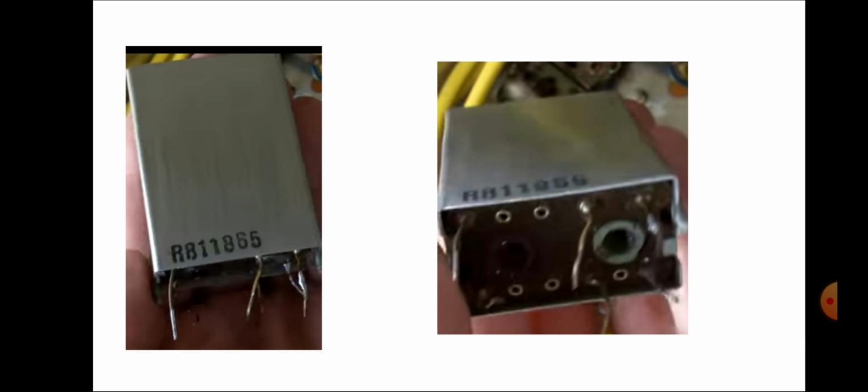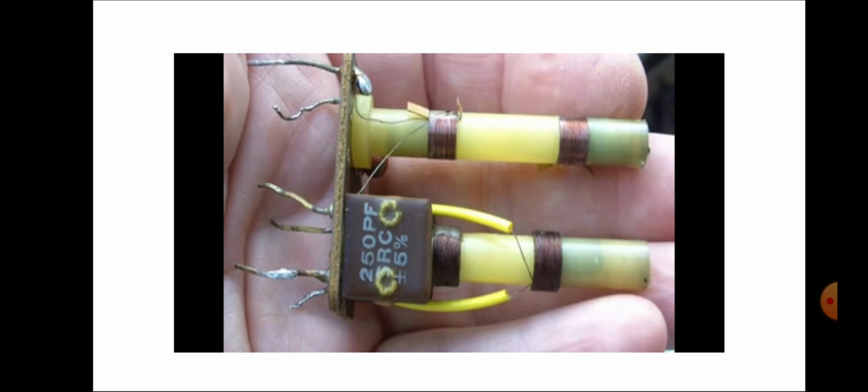It is available in the market. It has a shield, and it has two IF transformers as shown in the figure that are shielded in the aluminum box. If we remove the aluminum box, we will see two types of transformer. Here are two IF transformers, one is the AM-IF and the other is the FM-IF for the radio. Here the primary and secondary of the upper transformer and the primary and secondary of the lower IF transformer can be seen in the picture. In this picture the capacitor is fixed but the inductance is variable. Here by moving the core, we can change the value of the inductance.